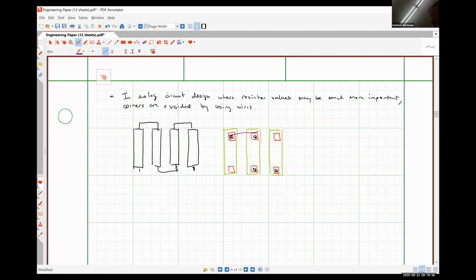Although, instead of extending beyond the N-wells in the top or bottom direction to wire these guys together, it's done higher on the z-axis. Yeah, anyway, sorry, just kind of jumping ahead, but I wanted to make sure to explain that you're not increasing the footprint of your resistors by including the wires.